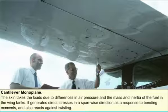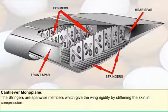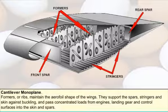It generates direct stresses in a spanwise direction as a response to bending moments and also reacts against twisting. Stringers are spanwise members which give the wing rigidity by stiffening the skin in compression. Formers, or ribs as they are sometimes called, maintain the aerofoil shape of the wings, support the spars, stringers and skin against buckling, and pass concentrated loads from engines, landing gear and control surfaces into the skin and spars.